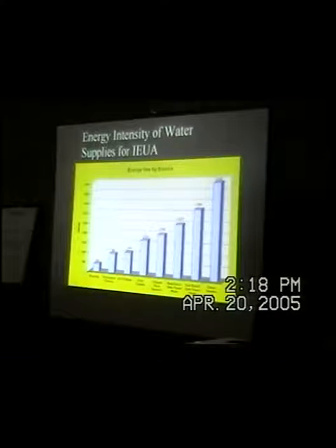This is real data for one utility that I like because they have a whole variety. It's hard to read that, but the low left there, this is in kilowatt hours per acre foot. So the metric is energy units per water, is recycling. By the time you treat wastewater to legal discharge requirements, the marginal amount of energy to treat it one more step and then be able to use it is actually pretty small. The next one's groundwater in their case, and of course that varies due to depth and so forth. That's about 950. Ion exchange, that's a desalting for lightly contaminated salted water, say from dairy operations and so forth. Then they have a reverse osmosis, RO system for groundwater desalt, and that's coming in about 1700.